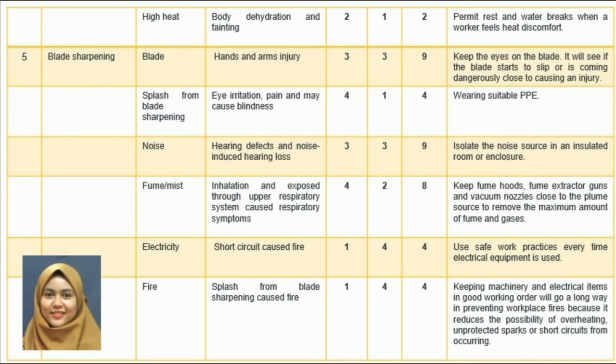The third hazard is noise. The effect is hearing defects and noise-induced hearing loss. The risk assessment is 339. The recommendation is isolate the noise source in an isolated room or enclosure.